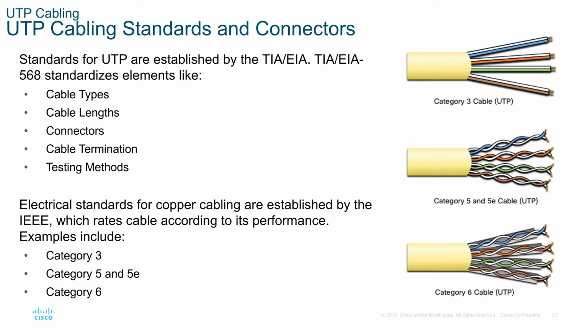Now, this diagram is not the best because it looks as though the wires are shielded. They are not shielded. If we were to look in the end of the cable, there is a plastic insert that keeps the 4 pairs of wires separate. And as such, we can run Category 6 at much higher frequencies.